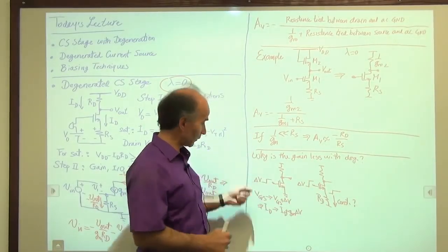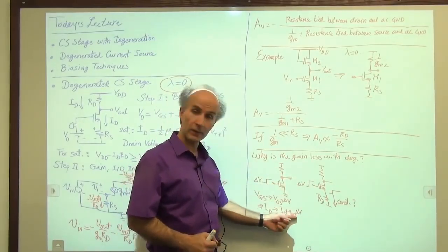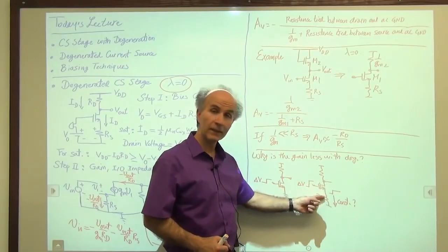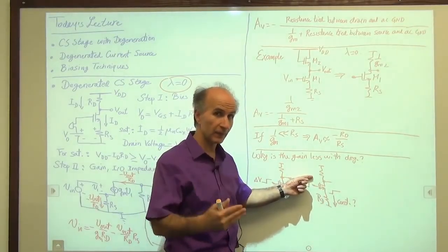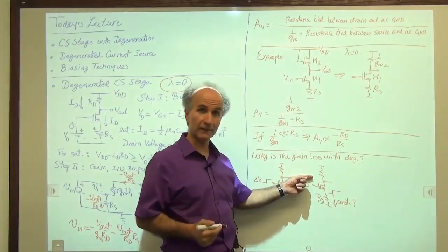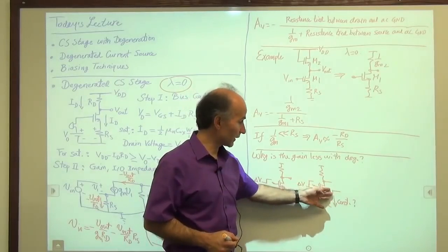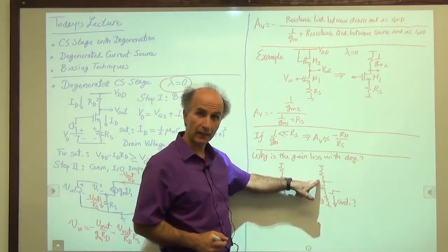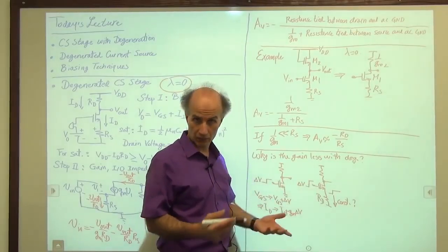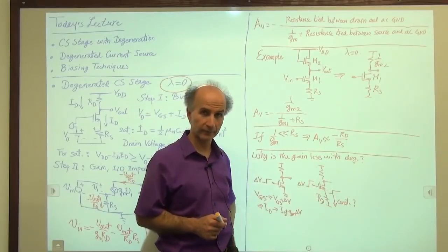From that GM, it would convert a change in voltage to a change in current, right, according to this equation. But this resistor has weakened it, so when we give it a change of delta V, it doesn't give us GM delta V. It gives us less than that. Okay? So that's why this circuit has less gain than this. The resistor has weakened this device. It's also linearized the device, and as a result, the gain has dropped.